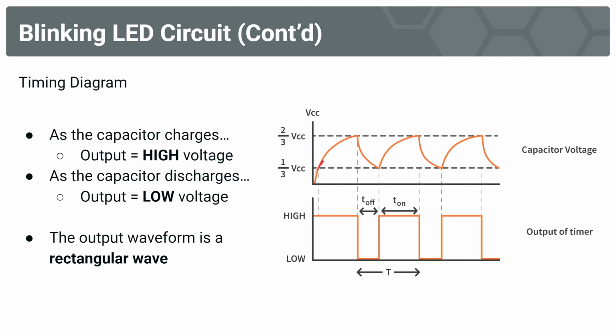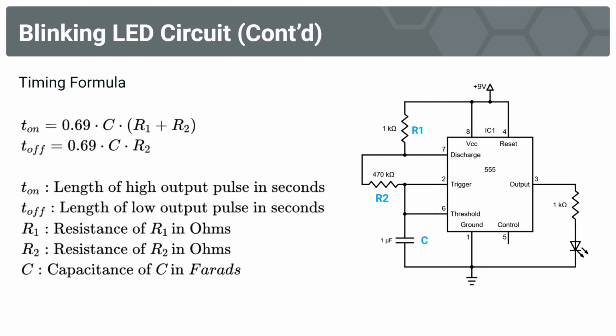And so you see this sawtooth waveform over time of the capacitor charging and discharging, and you can see it align with the LED turning on and then off. The time which the LED is off and the LED is on is loosely connected to our formula tau equals R times C. So hopefully now we're connecting the dots.